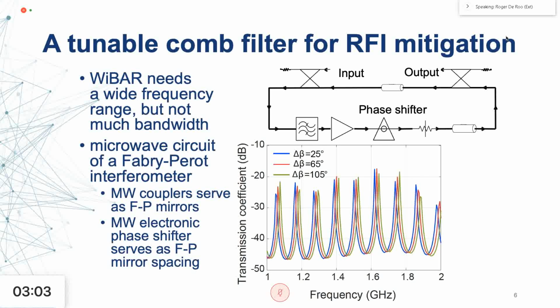The approach is to make measurements of the total power coming through, and where the power is minimized, that is a point where the RFI is also being minimized. And unlike traditional radiometry, because we're looking for a time lag and not looking for a magnitude like a brightness, we can sustain quite a bit more RFI in our measurements and still get pretty decent results out of the whole thing. Next, please.